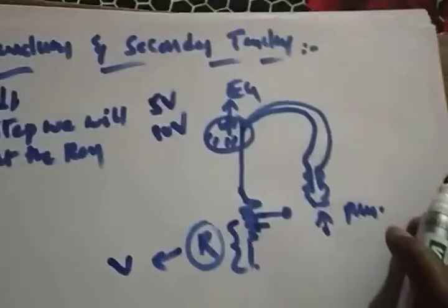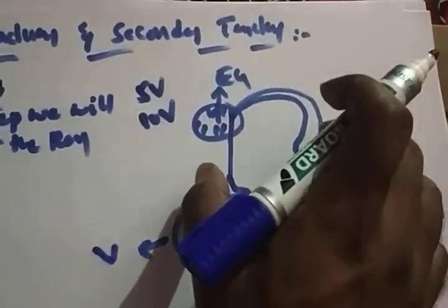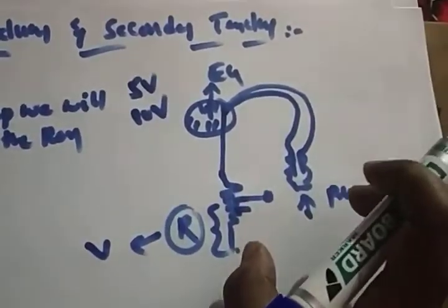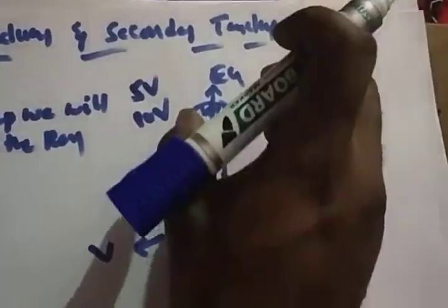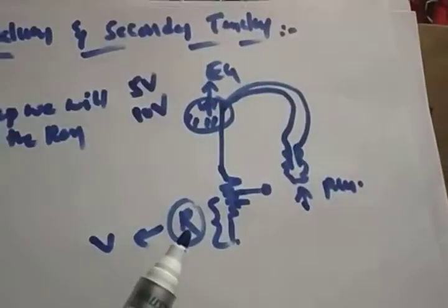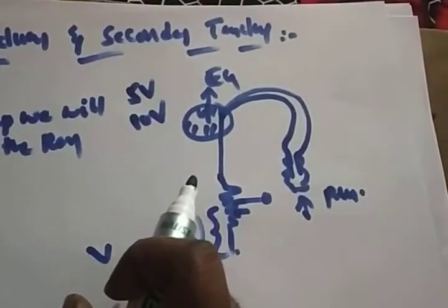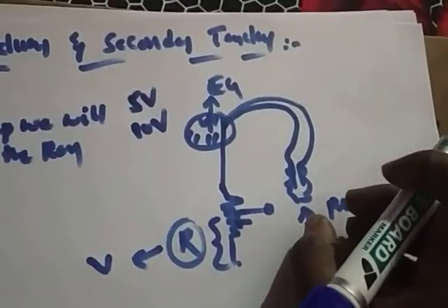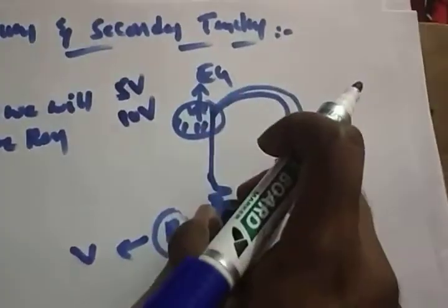One more time I'll explain. What is a primary transducer? Directly one step. If you want to find how much pressure, in one step you get the result. You apply a pressure, there is a meter, and it displays the electrical energy. What does a secondary transducer mean? We are taking too many steps. First, the pressure is converted to linear displacement.